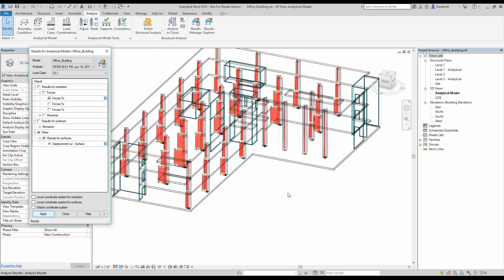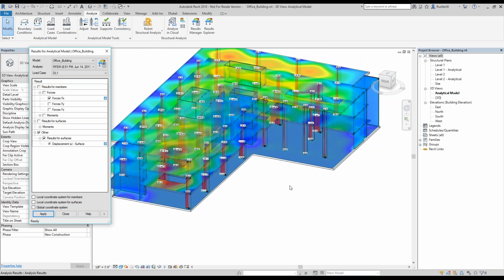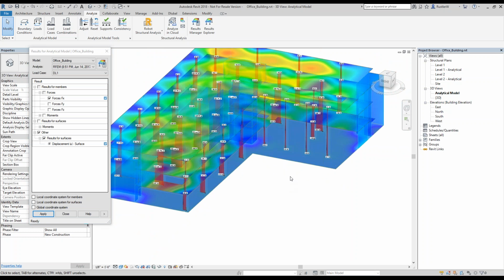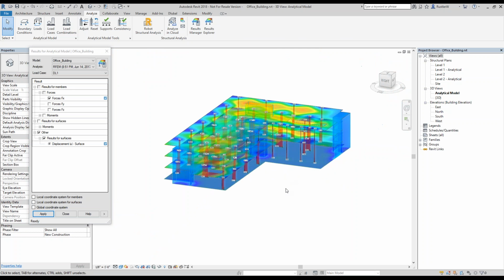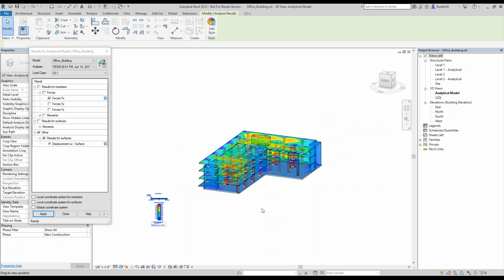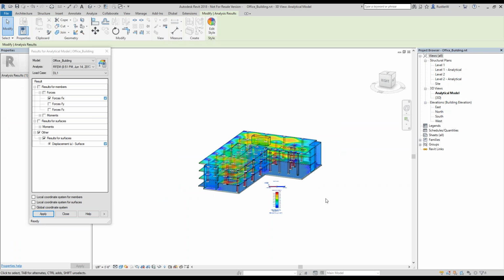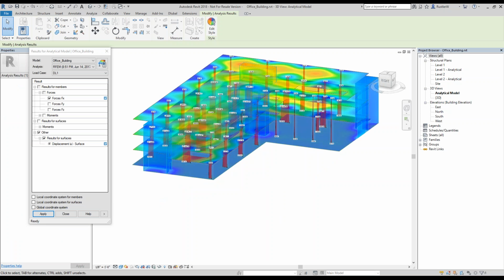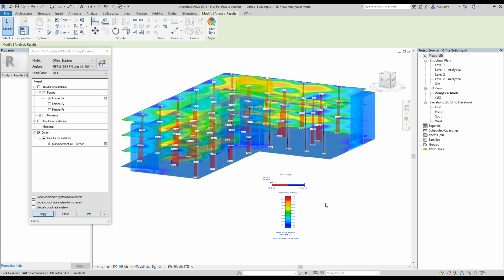displacement color maps. Yeah? That you can show. And this you can put on your drawings. You also have a little scale here, so I understand what the colors are for. Yeah? So this is a way how you can digitally transfer your calculation results into Revit, and all the other applications that can read the result packages can actually look at this. Yeah?